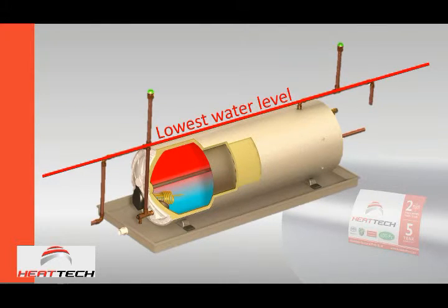So the only way to get the water flowing through the geyser again is to get the pressure up, to force pressure again from the inside through the geyser, and to fill the tubes up to the vacuum breaker again.